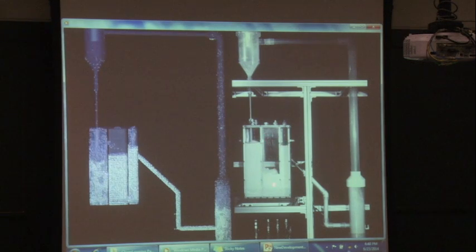When it gets too full, it dumps over into here. This is the region where, if this were a hot system, we would add enough air to fluidize it and kick the ash particles out of the bed, and then you'd collect those, and then the thing spills in this design out the bottom, up through, and then that forms a loop seal to keep this separate from the airstream over here.